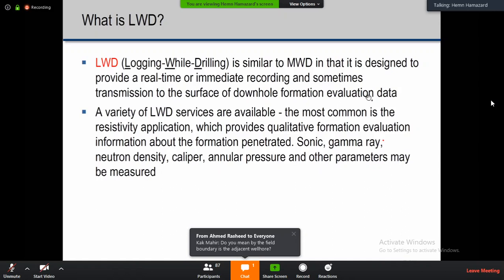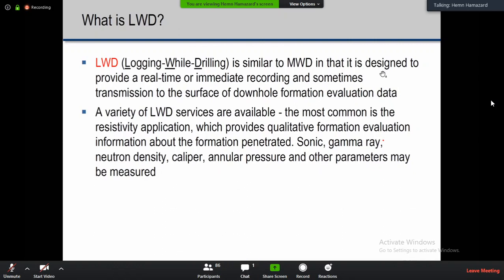As I mentioned before, for all wells in the area of interest, the 6-inch hole is over 45 degrees. And we have a lot of hole problems, like losses, washouts, overgauge, caves. So it's very, very risky to run wireline. Even if you run it, there's a very slim chance to be successful because your hole is already over 45 degrees. The wire cannot push the tools down.